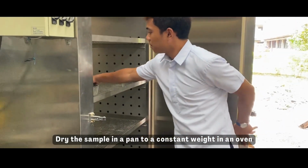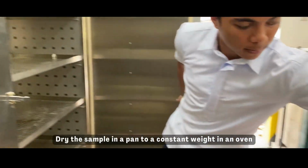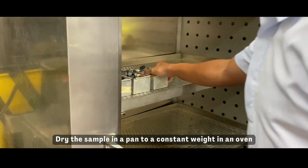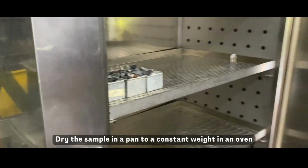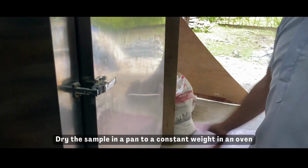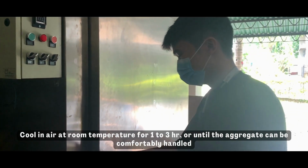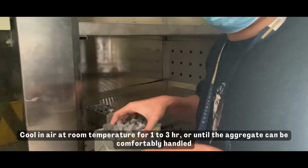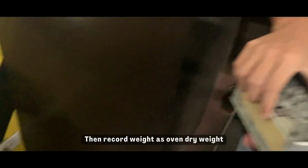Dry the sample in a pan to a constant weight in an oven for 24 hours. After 24 hours, cool it in air at room temperature for 1 to 3 hours or until the aggregate can be comfortably handled. Then record the weight as the oven dry weight.